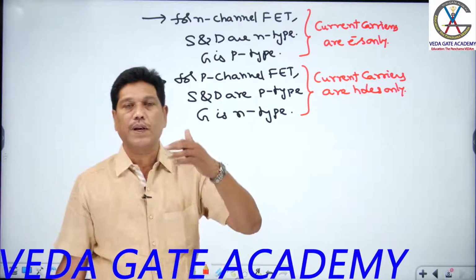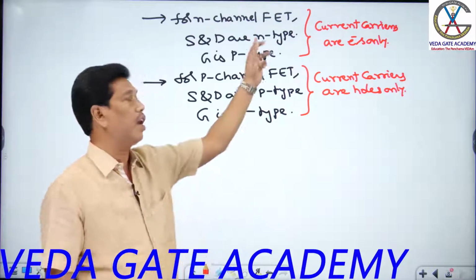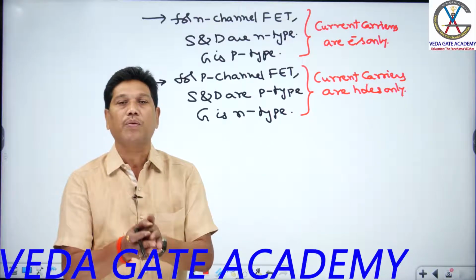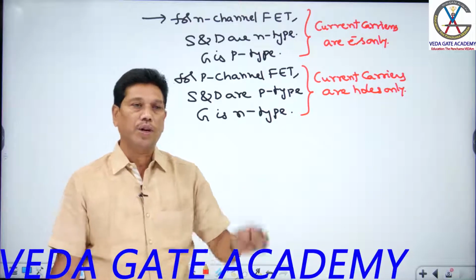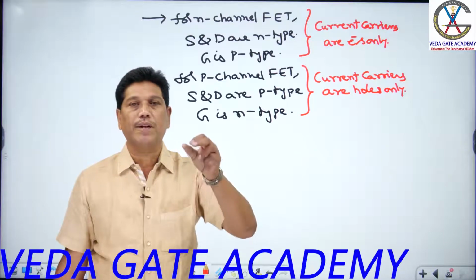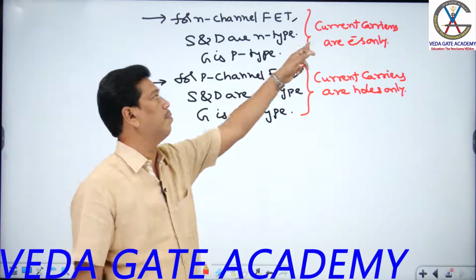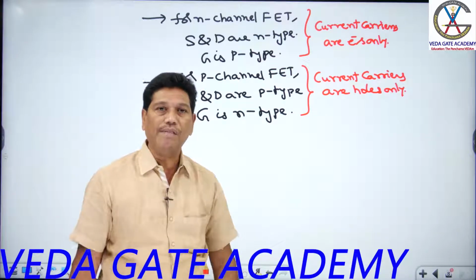So who causes faster conductivity, sir? N channel body compared to P channel body. So N channel body has a good packing density over P channel body, which is why it is mostly preferred. N channel FET is superior and preferred compared to P channel FET. The main reason is that the mobility of electrons is greater than the mobility of holes, students.